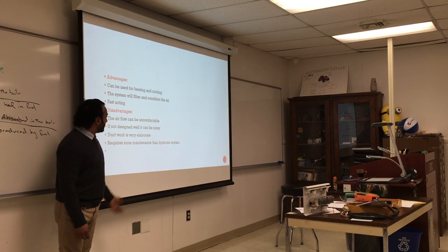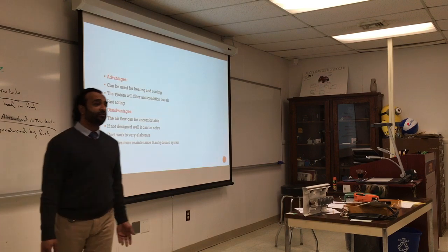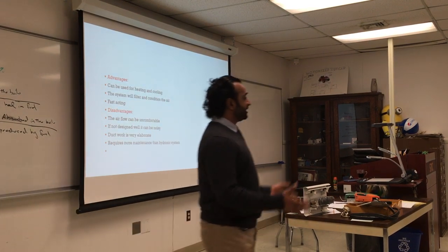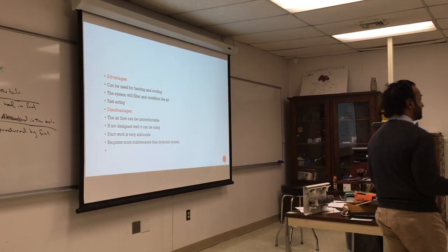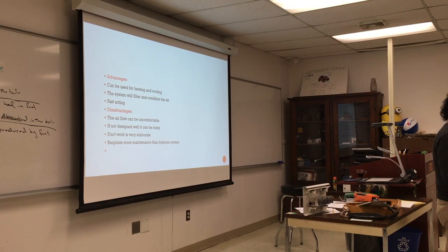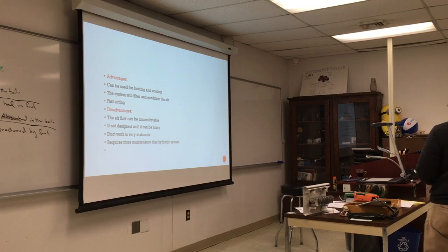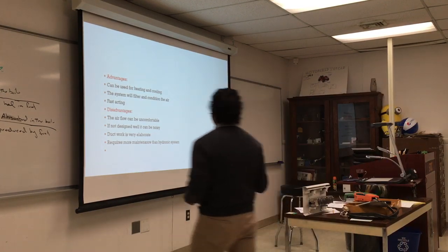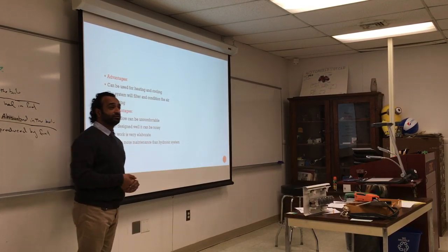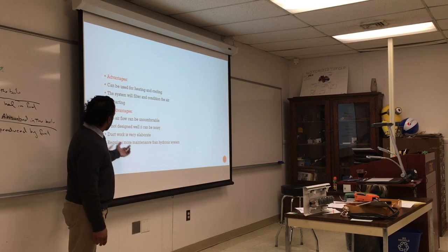If it's not designed very well, it's going to be very noisy because, again, as we said, you can have registers that are very small. So to compensate for the size, you're going to shoot up really fast air, and that will stir up and produce a lot of draft, and it's very uncomfortable.